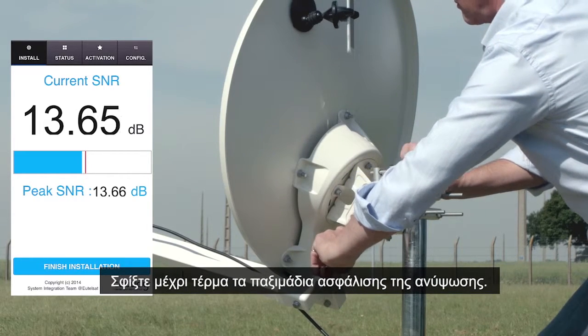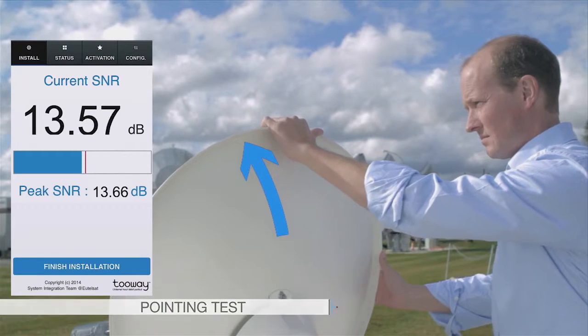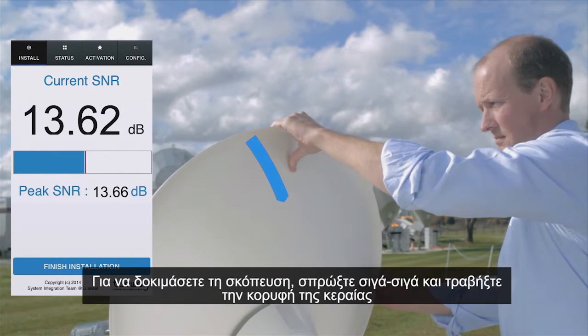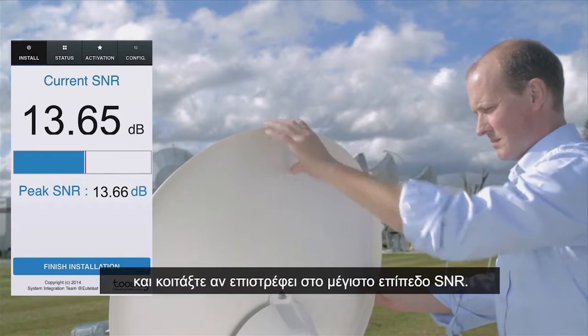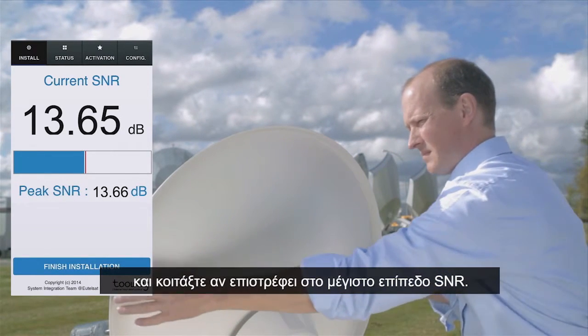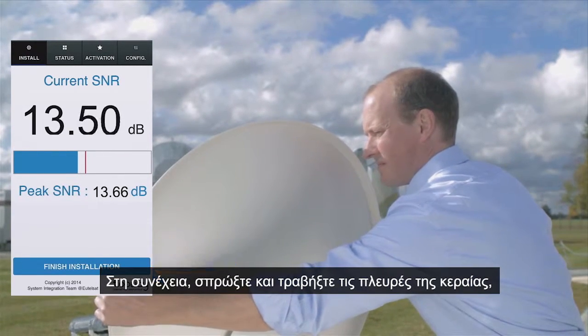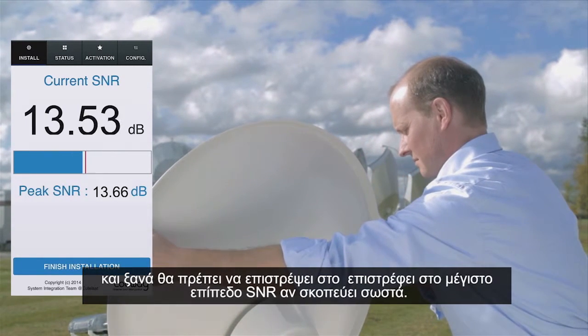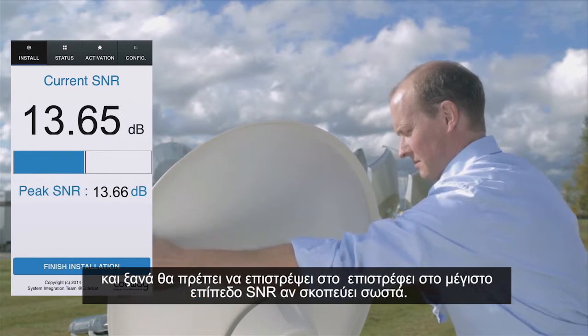Now you tighten off the elevation locking nuts as tight as possible. To test the pointing, gently push and pull on the top of the antenna and see if it returns to the SNR max level. Then, push and pull on the sides of the antenna and again it should return to the SNR max level if it is pointed correctly.